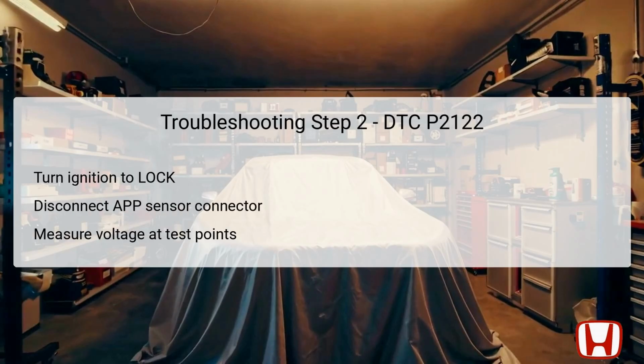In Step 2, the objective is to determine the possible failure area by checking the voltage supply to the APP sensor. Begin by turning the ignition switch to the lock position to ensure safety before making any electrical connections or disconnections. Disconnect the APP sensor 6P connector to isolate the sensor from the circuit.